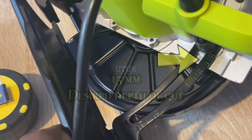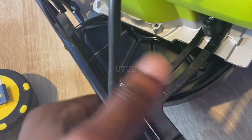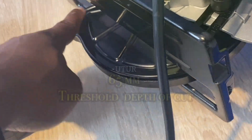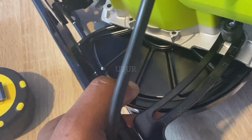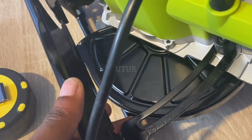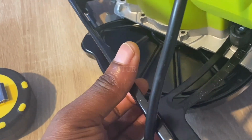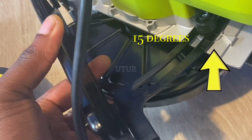And so here I will be reducing the maximum from 65 to about 15 on the scale. And so this is what 15 looks like. Initially it was 65, and you can see that it's got too much clearance. So I'm going to reduce that to 15 on the scale. And once it's 15 on the scale, I will push the lever down to lock it in position.